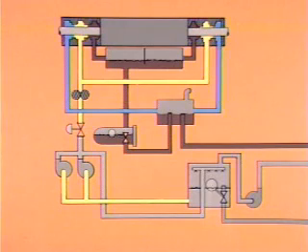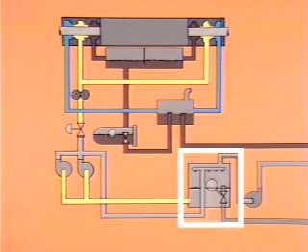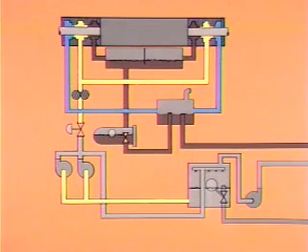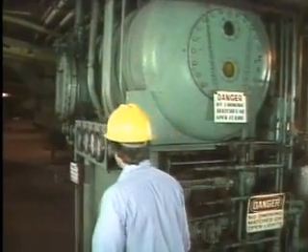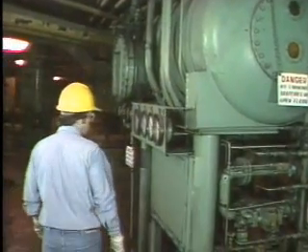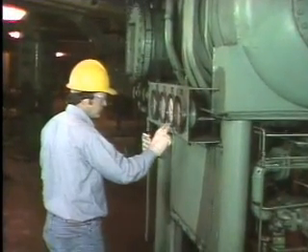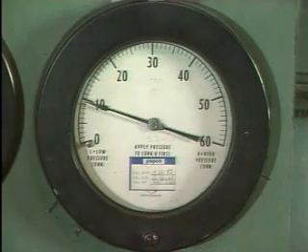After the air and hydrogen are separated from the oil and vented to atmosphere, the seal oil is recirculated to a vacuum treatment tank. To ensure that the oil continues to flow through the system, a circulating pump maintains the oil at a slightly higher pressure than the hydrogen. The difference between the oil pressure and the hydrogen pressure is called the pressure differential.